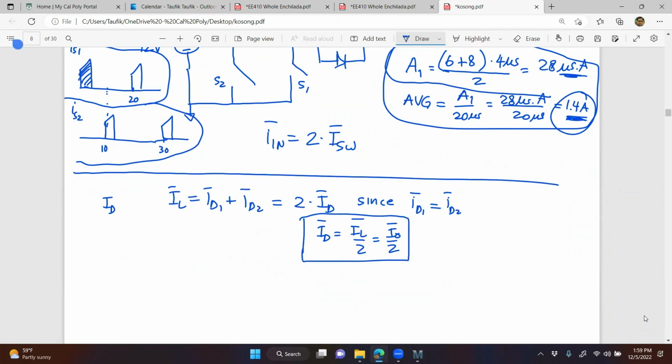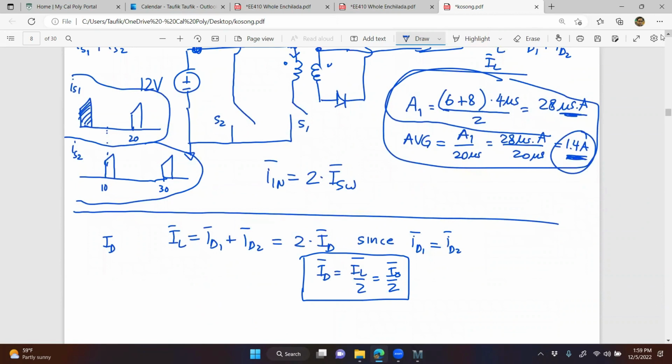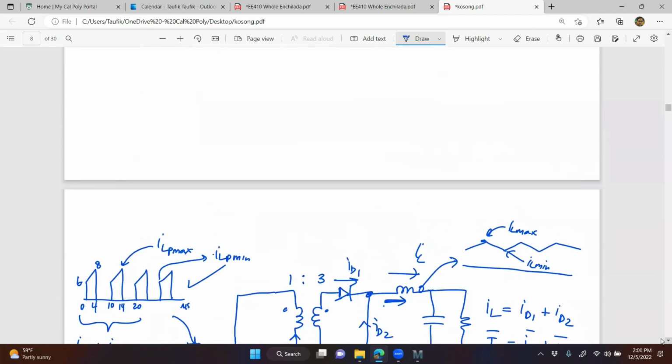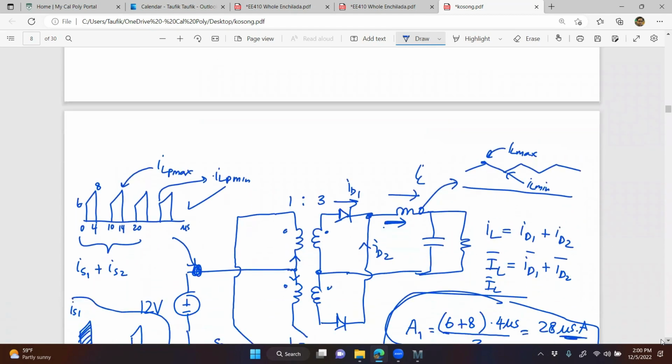Any question on this? How can we use that instead of our duty cycle equations, like I diode equals I inductor times 1 minus duty cycle? Not anymore, not on push-pull. Because in push-pull we have 2 switches, and when the switches are off, the diodes are still conducting.